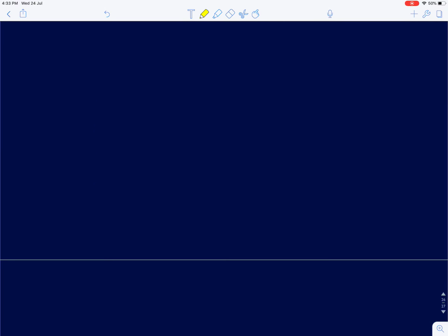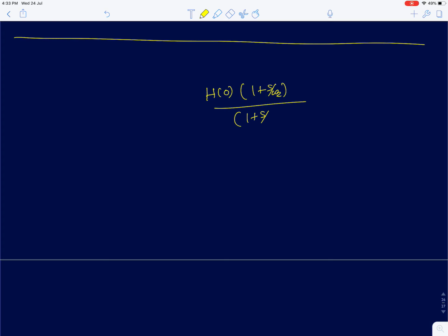Okay, so now we will go about analyzing a general transfer function of a first order system, which is with a finite 0 and a pole. Now this function, again, we have already written it as a sum of a high pass and a low pass transfer function.